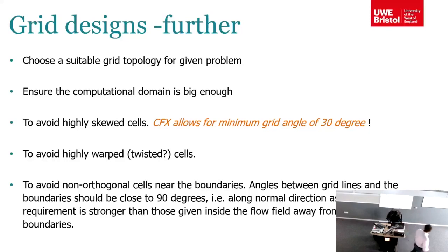On the other hand, if you are modeling, say, a building or atmospheric flow, you can't go small in grids. Your grid may be about 1 meter by 1 meter sometimes when you do atmospheric flows. You can have very high resolution, very small grid cells at the boundary layers, but not in the other areas.